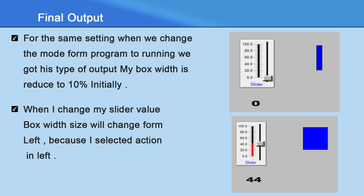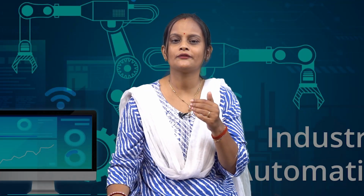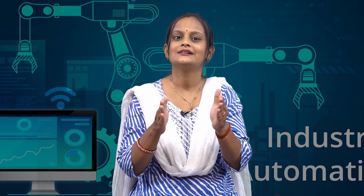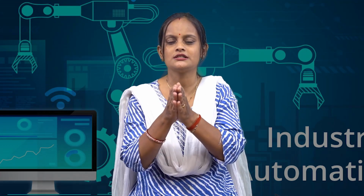When I keep increasing my slider and move it upward towards 100, my box width will change from the left, because in the action I have selected left. Now if you select right in the action, the size will change from the right side. If you select center, then it will expand from the center. So you can set anything: left, right or center.